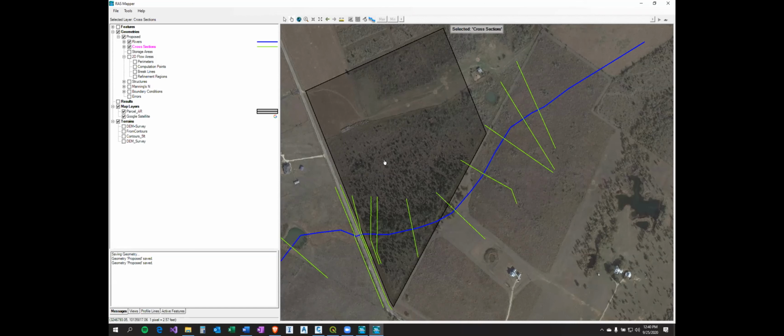You said that is through Civil 3D? Yes, it's the river analysis tools. Okay. And Courtney, I'd strongly recommend against using those river analysis tools. Autodesk acquired that software, hired a guy to foster and manage it, and that guy no longer works for Autodesk anymore, and it's become a little bit of a bastard piece of software, to be honest. It's unstable. That's what Adam's running into. And anybody that I've ever talked to that's asked which way to do it, I would recommend the way Adam showed it every time.